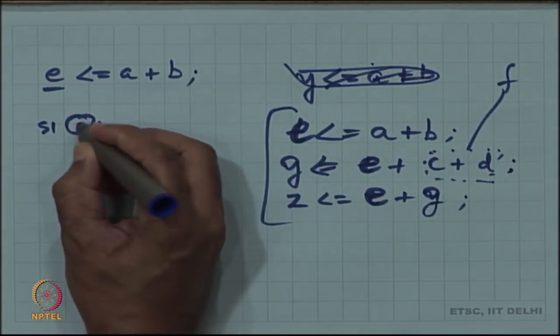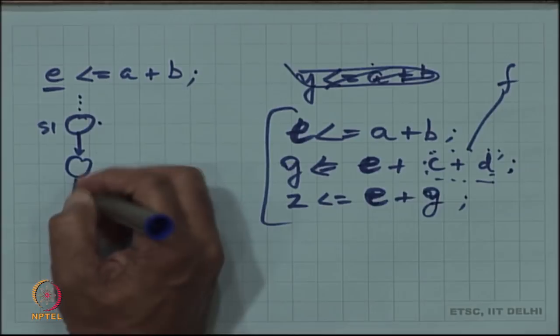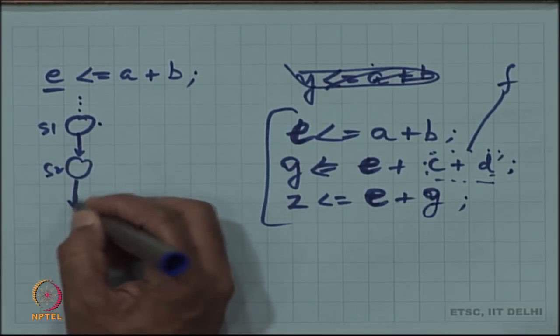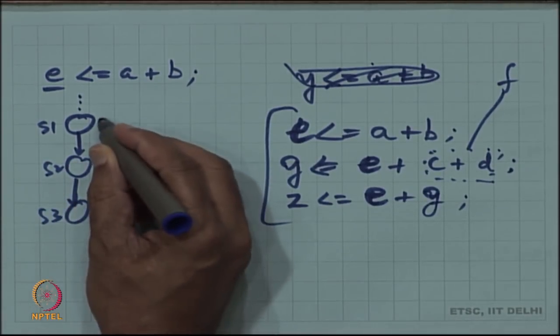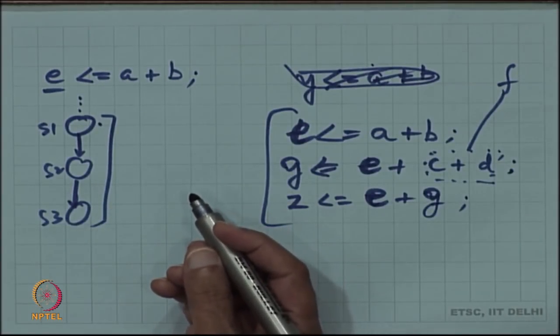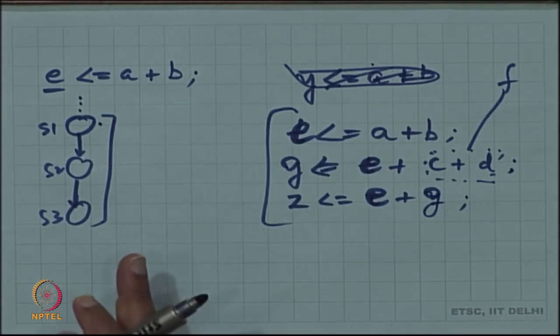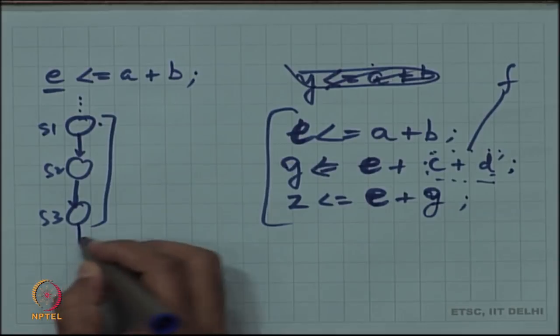If this was my first state, and there were other states before, I just introduce 2 more clock cycles, right. If I know it is taking 3 clock cycles, then I just introduce 2 more dummy states in the FSM, and pick up its value later on.